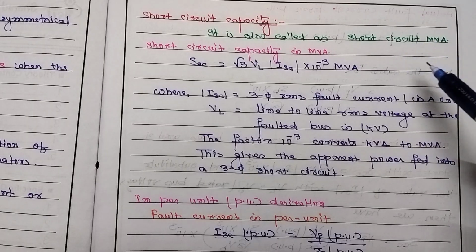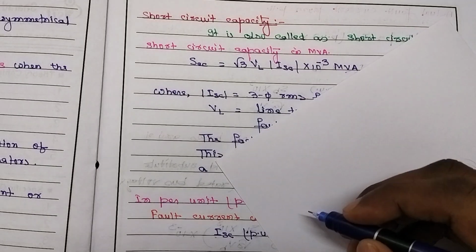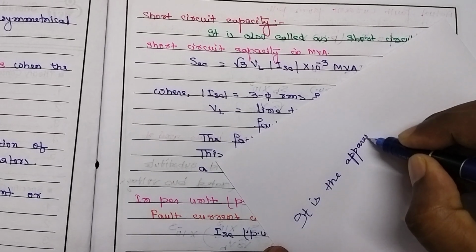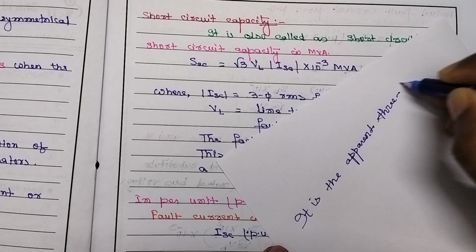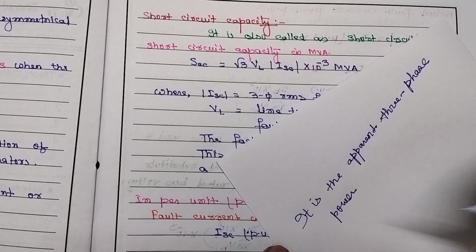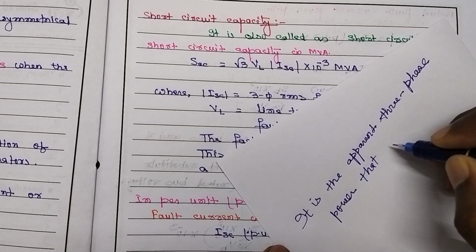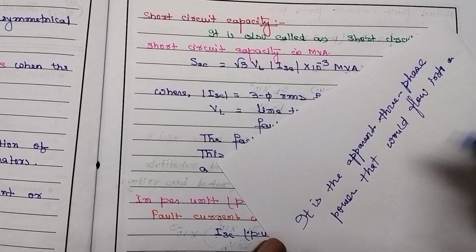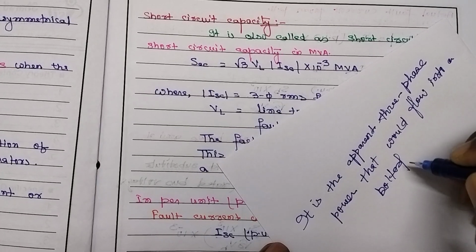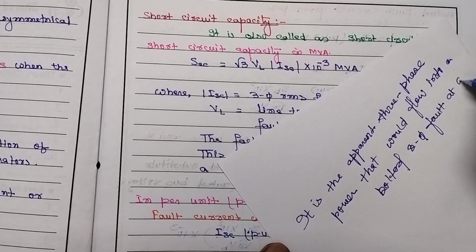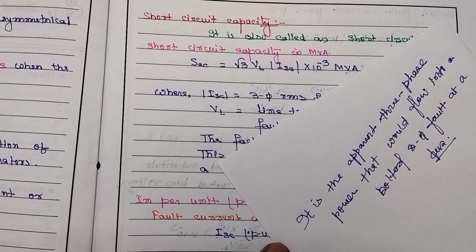The word itself shows that it is the apparent three phase power that would flow into a zero-voltage three phase fault at a bus.